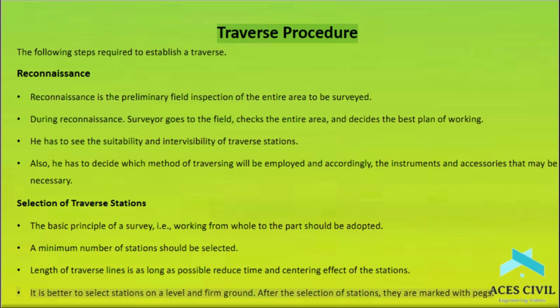Traverse procedure. The following steps are required to establish a traverse. Reconnaissance. Reconnaissance is the preliminary field inspection of the entire area to be surveyed.